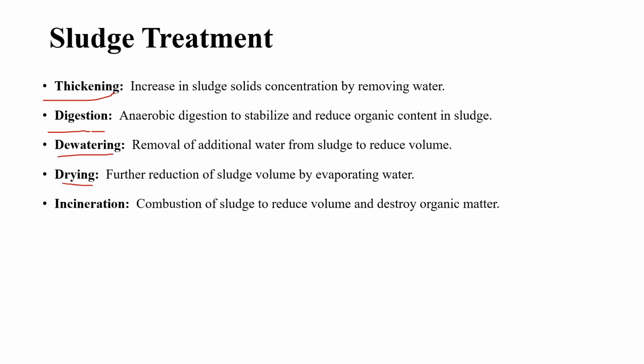Drying is nothing but a dewatering process. And finally, the incineration process, the removal of all the organic matter and water content in the sludge, and again it will be distributed to agricultural land. These are the important sludge treatment processes that take place at last, for the waste produced from water treatment.